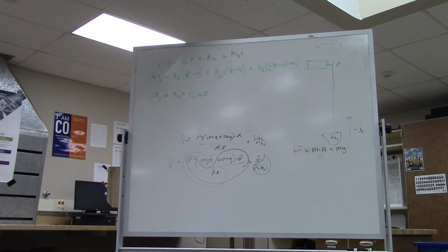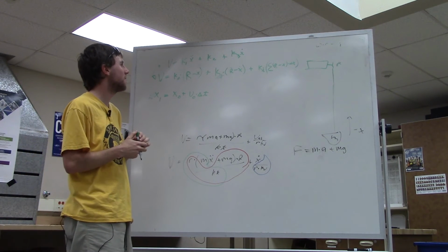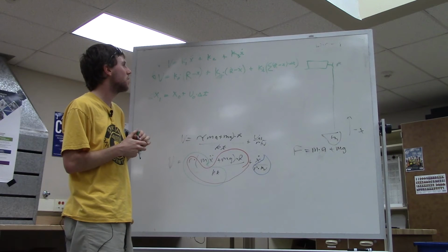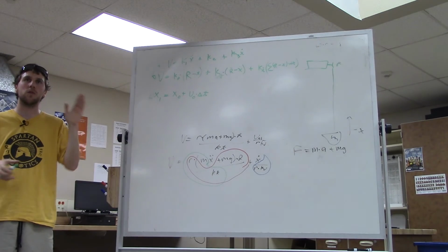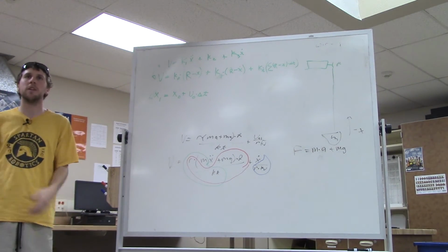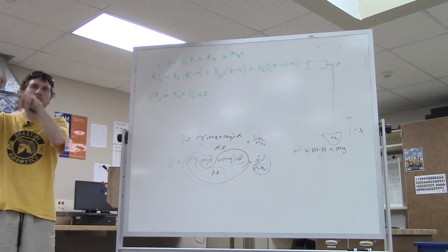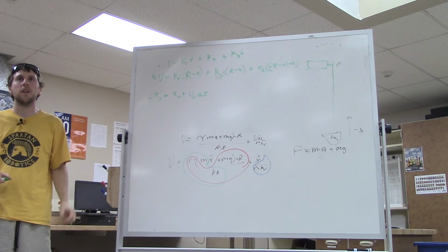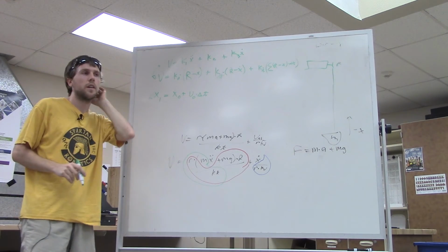When you guys are talking about filtering stuff, what is that? This is a rabbit hole we could spend the whole day on. So one form of filter would be we're going to add the last 4 values together. So n minus 3, n minus 2, n minus 1, and the current. Add them together, average them, and return the result. What this is going to give you is that large changes are going to get smoothed out, and you're going to get a number. So kind of a noise reduction type thing? Yeah.